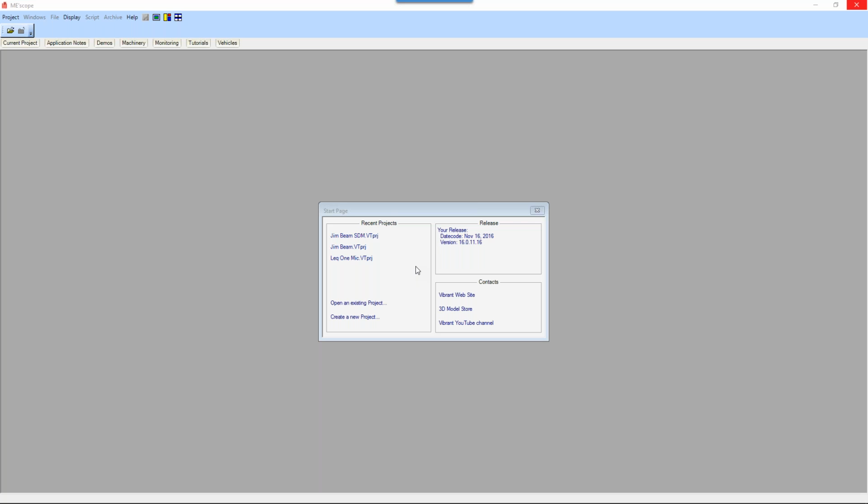Typically, if a mode is getting excited, if a resonance is getting excited in a machine or in a structure base or a building or a bridge, whatever, it's the low frequencies that dominate the response. And so those are the ones that we need to include in our modal model in order to obtain an accurate description of the dynamics.